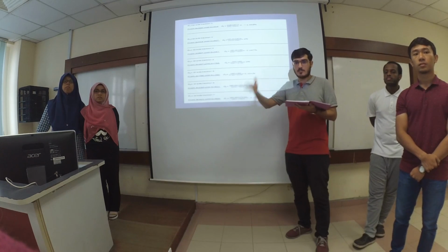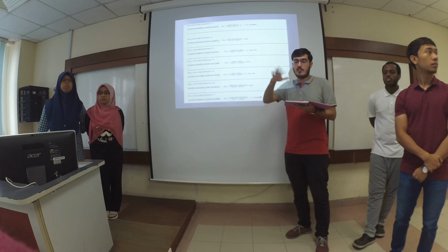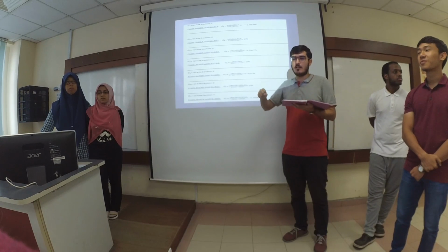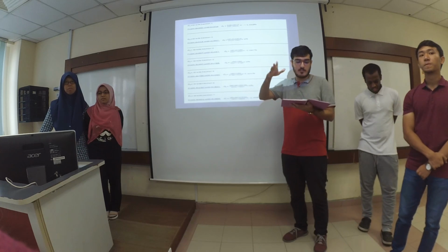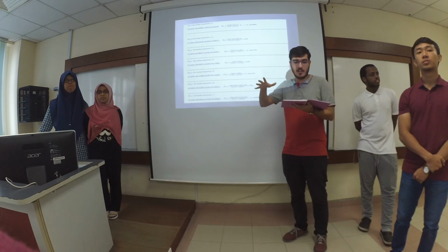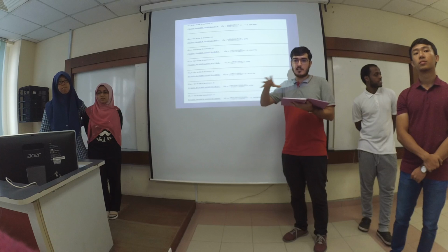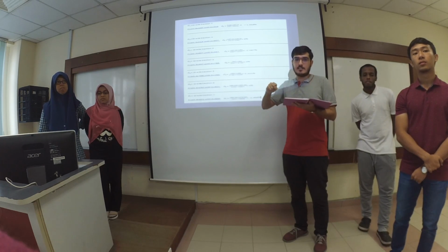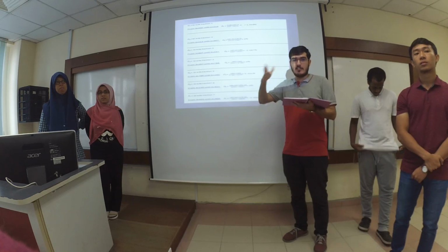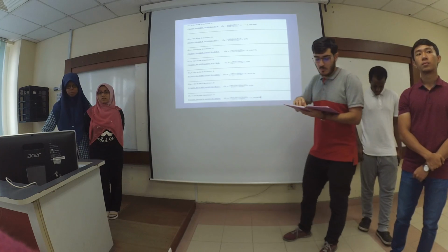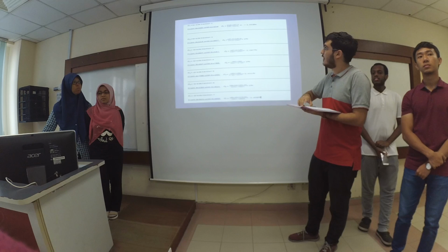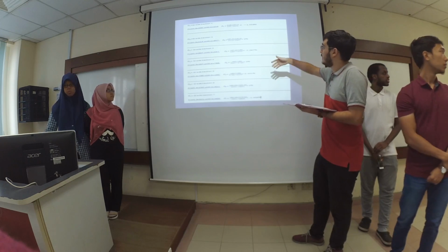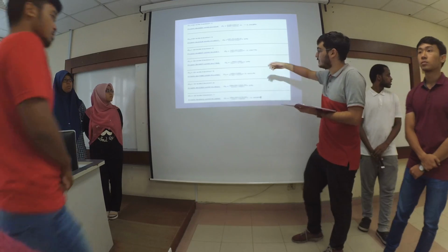And once it was transferred to the graph paper, we tried to come up with the vertical alignment of our proposed roadway with very suitable grade lines to make sure that it has a very safe and smooth variation of slopes. These are our grade lines, and as you can see, all of them are recorded below 2.1%, which is considered to be safe.